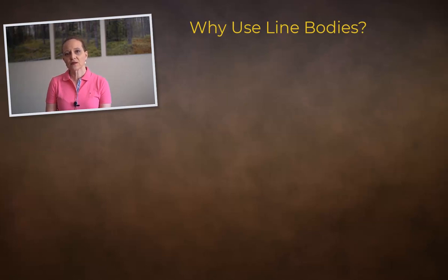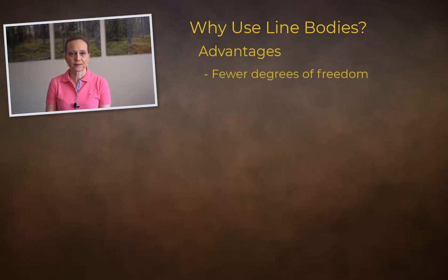However, in the case of slender structures, we may end up either with extremely high aspect ratio elements that act overly stiff and don't capture the deformation well, or with a very large number of elements that may have reasonable aspect ratios. Thus, by using line bodies when applicable, we end up with significantly fewer degrees of freedom while retaining higher accuracy.